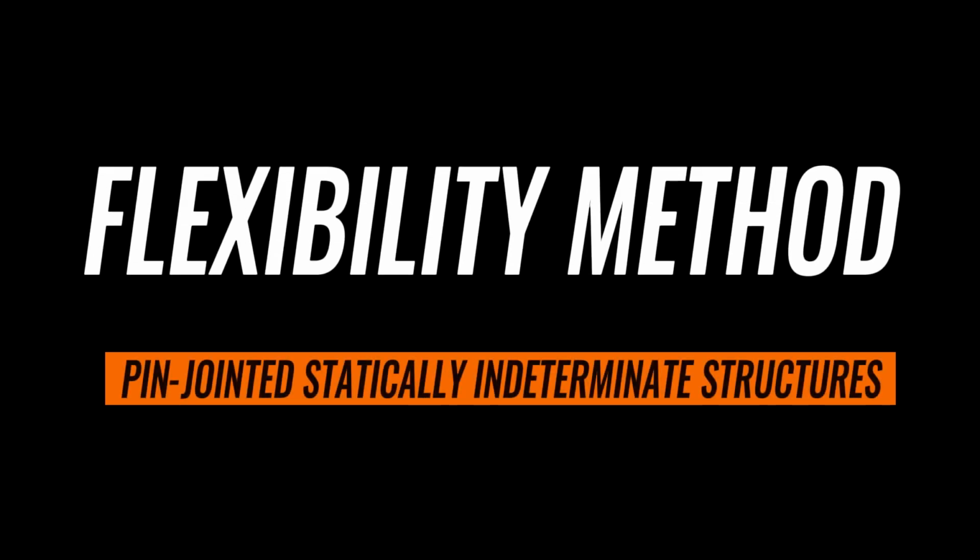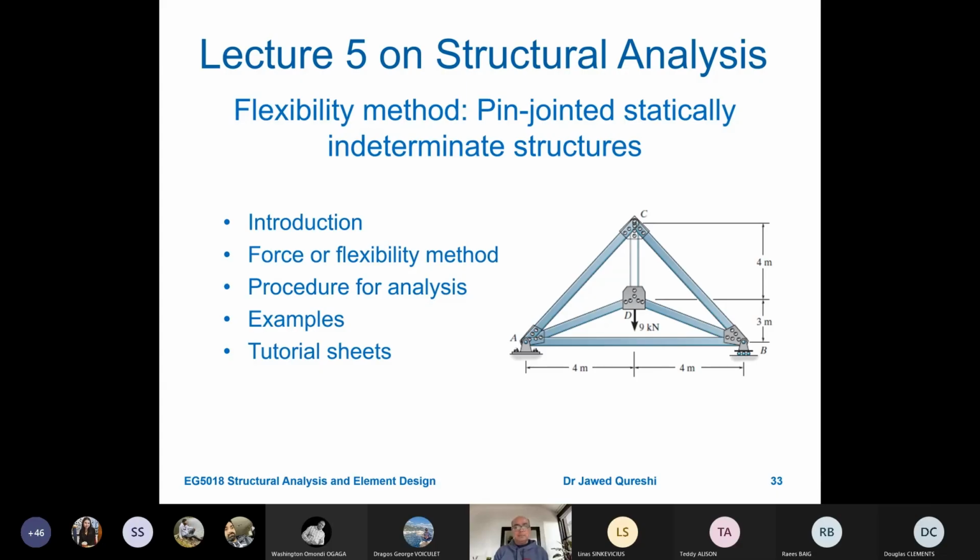In this part of the lecture, I'm going to cover the flexibility method for pin-jointed statically indeterminate structures. This is mainly applicable to trusses, which are indeterminate trusses. And the key thing here is to determine the member forces.